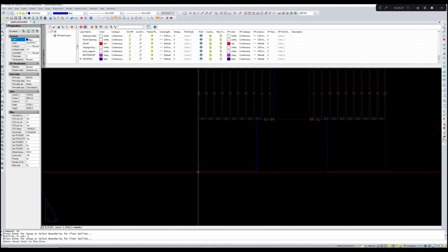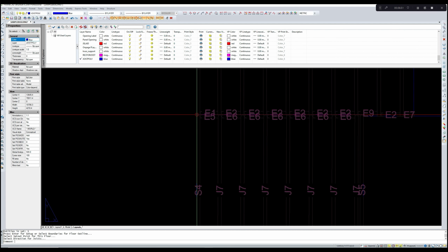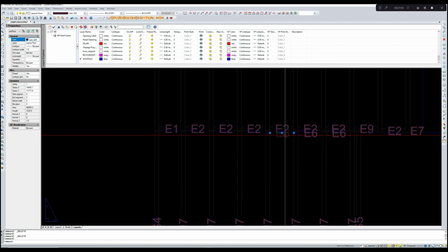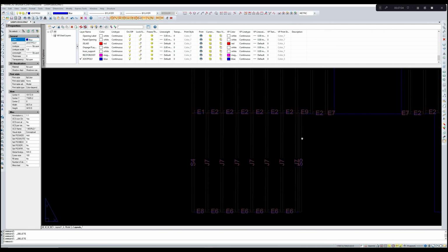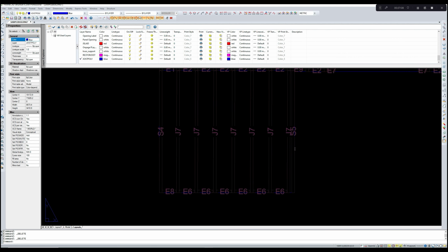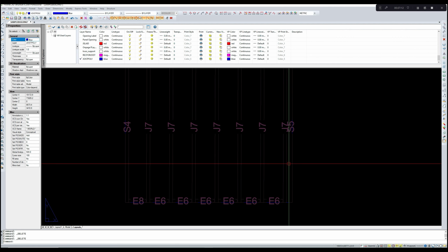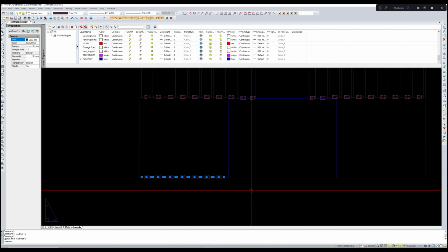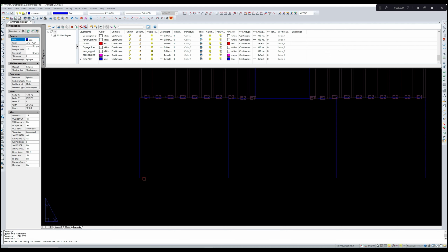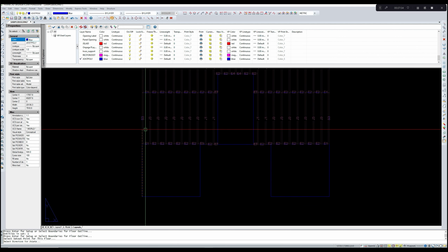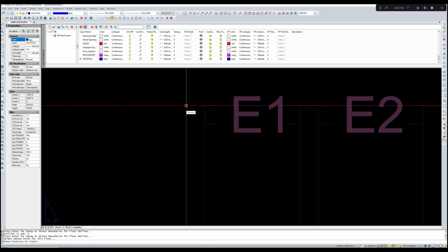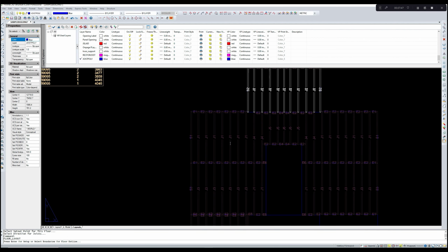Again JD, select this polygon, rectangle, give direction, enter. So we do not need this end plate and blocks. So we need to delete it. Now this joist has not been created properly. There seems to be an alignment problem, so let us delete them and create it again. JD, select the polygon, take it, give the direction, enter. Now this has been created properly.